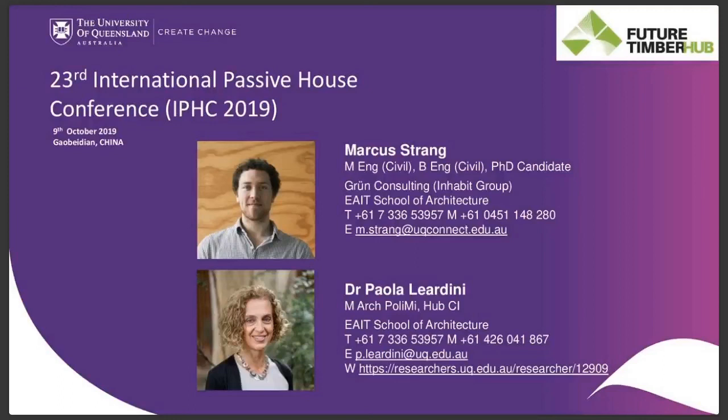So I've actually got another question, Marcus, for you, and that's from Marshall Gardner. Would a different species of tree from basswood be better for moisture handling or rot resistance? So is there, for instance, any variability analysis on the different types of wood? Yeah, definitely. So a lot of the CLT that comes out of Europe and even Australia at the moment is all softwoods. In Europe, spruce is used. In Australia, we use radiata pine.